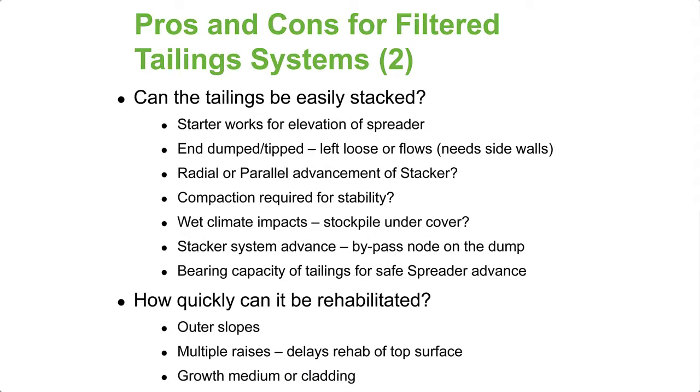And then there's the advantages or disadvantages of being able to rehabilitate the facility sooner rather than later. And if you're building it up in layers, then definitely you can rehabilitate the side slopes. If you're building it as an advancing face, you can rehabilitate from behind it.